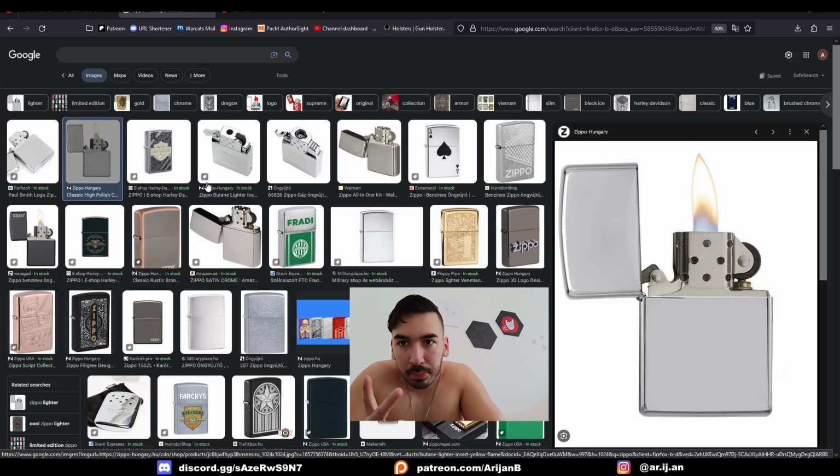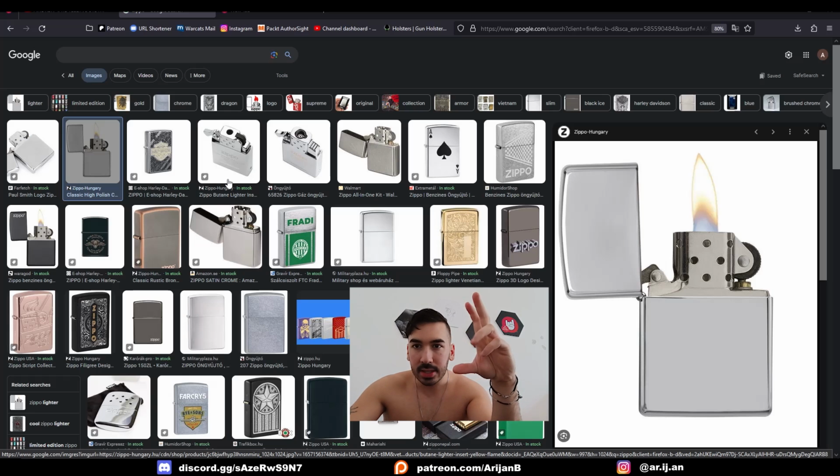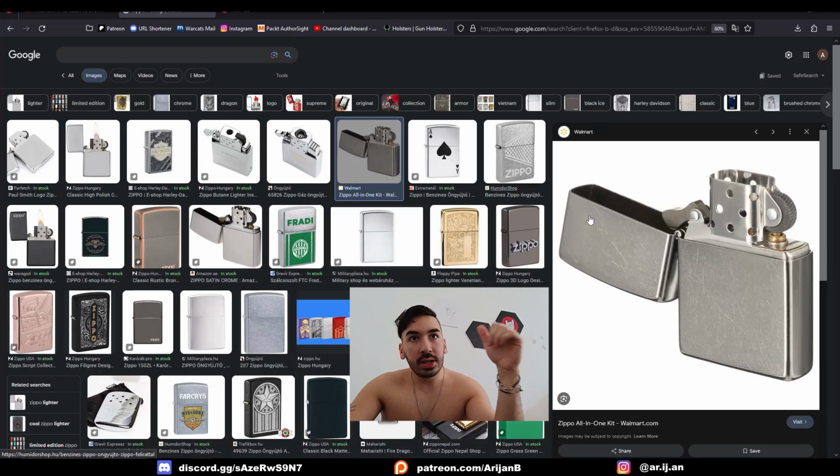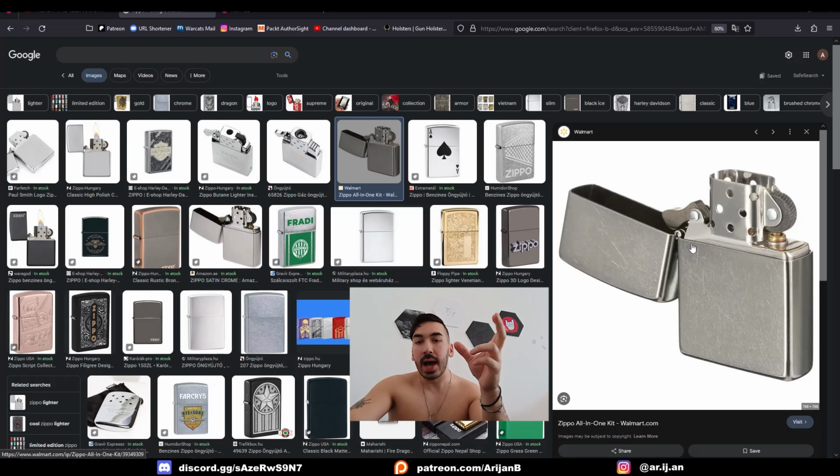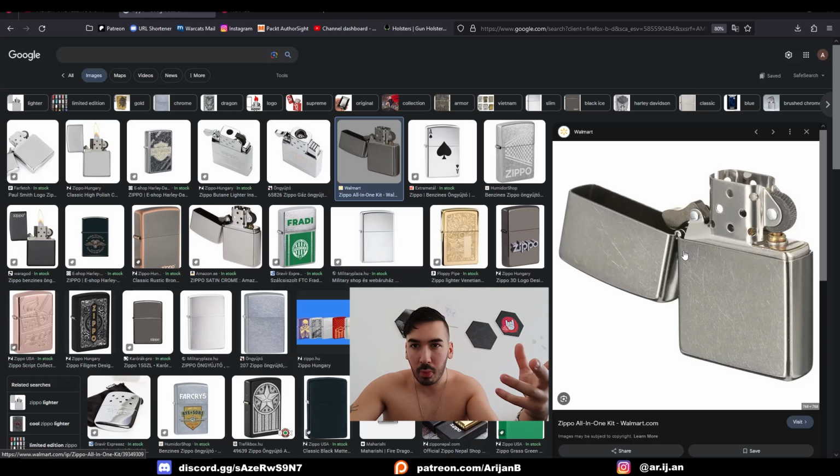We're gonna need two separate reference images for a project like this. We need one reference, which is gonna be like a blueprint. Ideally, this is just gonna be like a side orthographic projection picture, and we're gonna use this just for the dimensions and length and height and all this other stuff. And we're going to need another image, which is not really like a blueprint or an orthographic projection side picture. It's just gonna be like a 3D picture from the side where you can see the depth, you can see kind of the proportions of the whole thing.